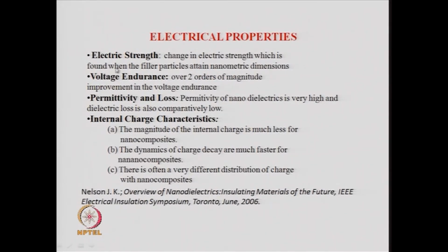So, one has to measure the electric strength of these devices with nanometric fillers. The other thing is the voltage endurance, how long you can apply the voltage. Over 2 orders of magnitude improvement is there when you go from micron sized particles to nano sized particles. So, this is a large change in the endurance of a material. That means this material can withstand voltages of much larger values for much longer times.